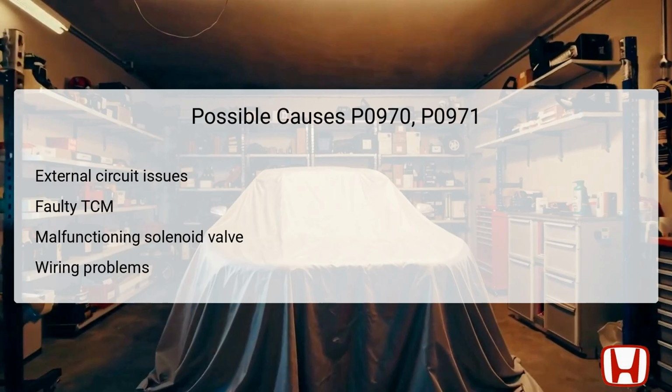It is also essential to consider wiring problems, as damaged or corroded wires can disrupt the flow of electricity to the solenoid. Each of these components plays a pivotal role in the function of the transmission, and diagnosing them correctly is crucial to mitigate further transmission complications.